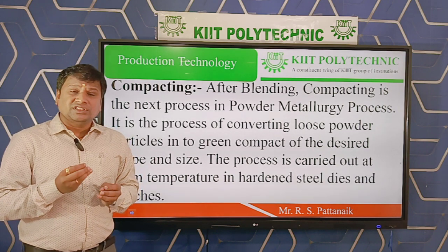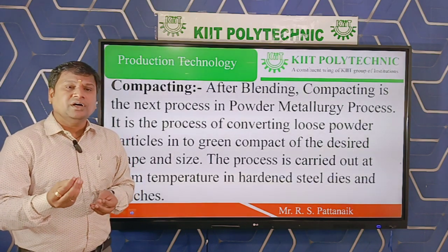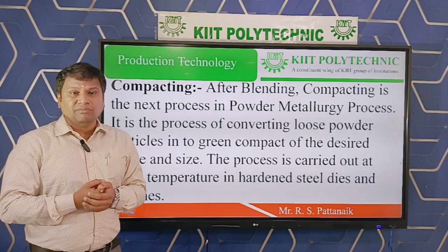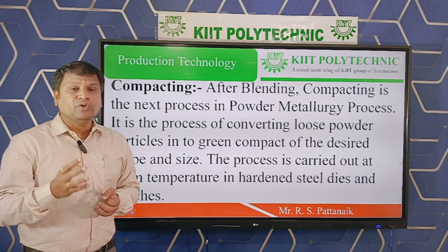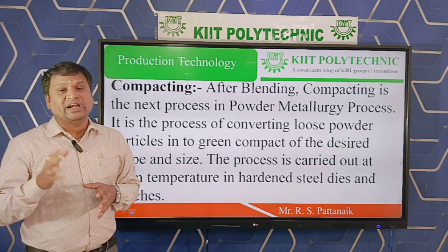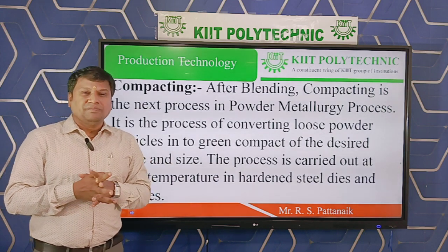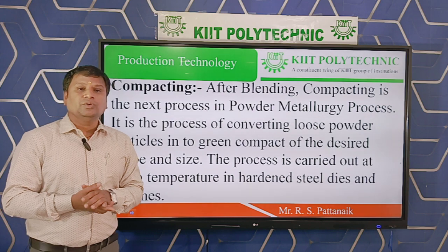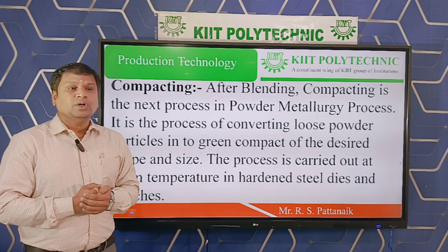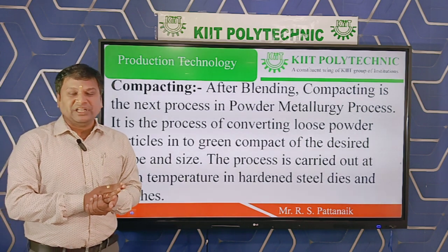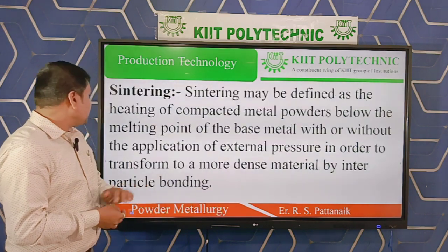Pre-sintering is the process of heating the compacted metal powder to remove the lubricants or binders added during blending. The temperature of pre-sintering is below the temperature of sintering. Okay, so next is the sintering.